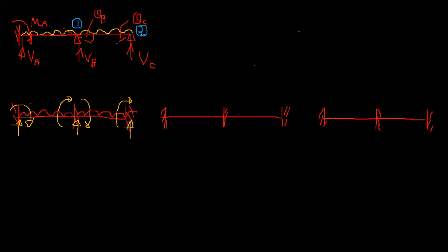So in the force method, we consider the compatibility, the shape at that joint. And most of the time, the original shape was 0, right? There will be no settlement in the supports, and even if it's the fixed support condition, right?